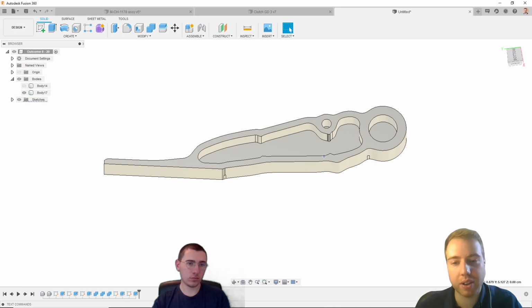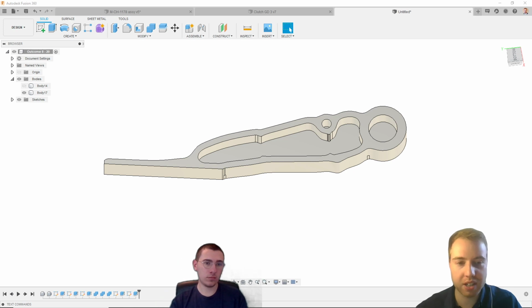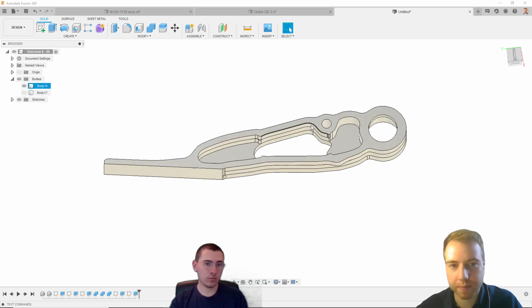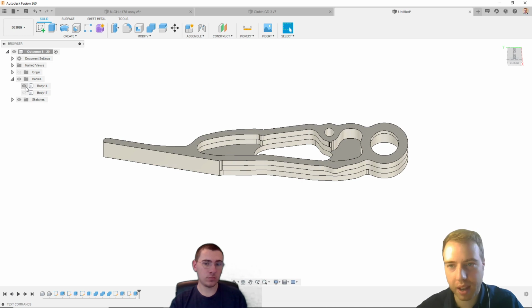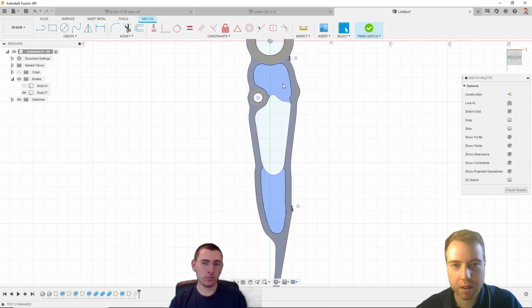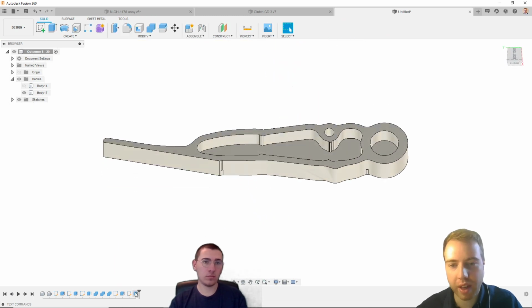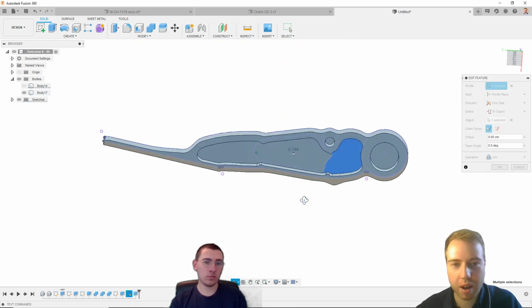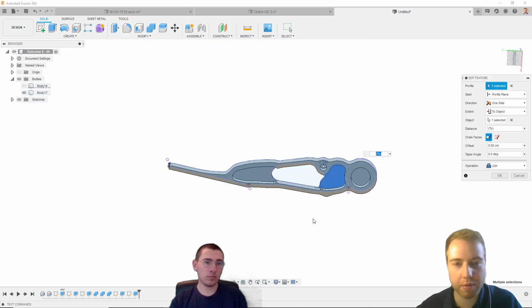And when you're doing this, you have to be a bit careful. Whenever you have these linked sketches like this, it's connecting from one thing to the next. So we go to this body here, and we need to make sure that our extrude recognizes that new profile.